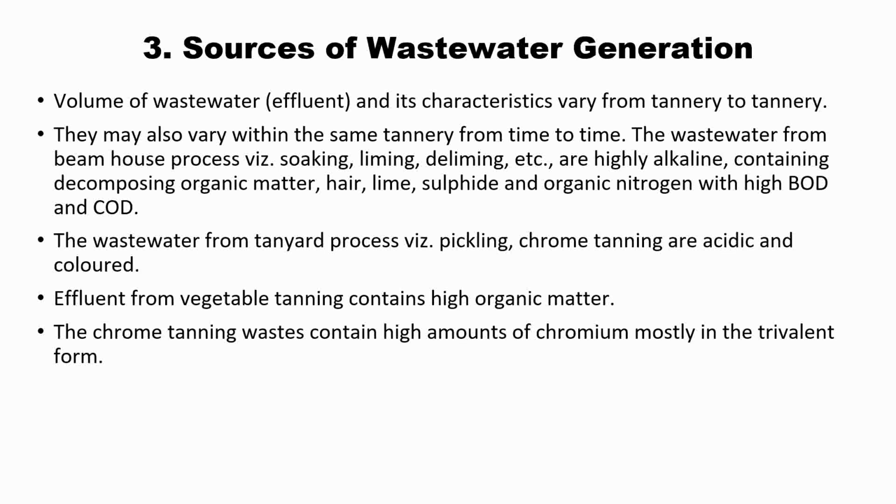Now moving toward the sources of wastewater generation. Firstly, the wastewater generated from a tannery is not the same all across the world. It depends from one tannery to another, as it is totally dependent on which types of processes you are involving. Some of them you may skip, or suppose you are going for chromium tanning, then the heavy metals in the wastewater will be much more than in the wastewater of vegetable tanning. So the concentration and characteristics vary.